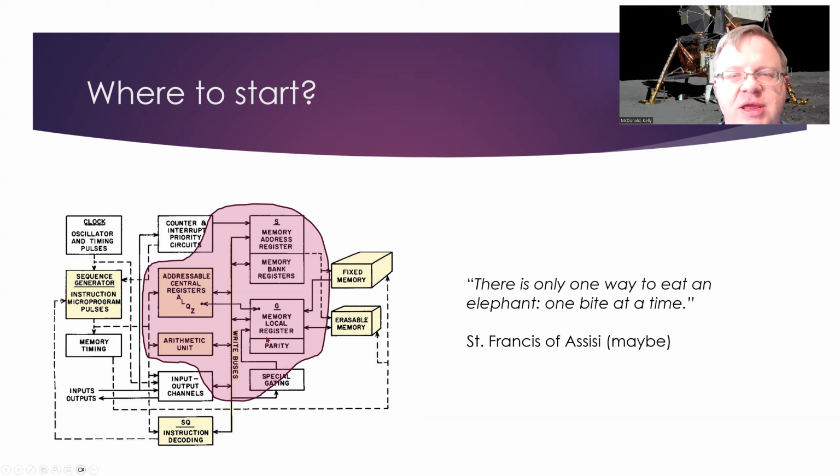So you have parity, which will always check to see, do we have an even number of bits in our particular word or an odd number of bits? Apollo guidance computer uses odd parity. So the idea is that if any bits get flipped in memory, you can at least detect that there has been an error, and reread that memory in order to correct that particular error.